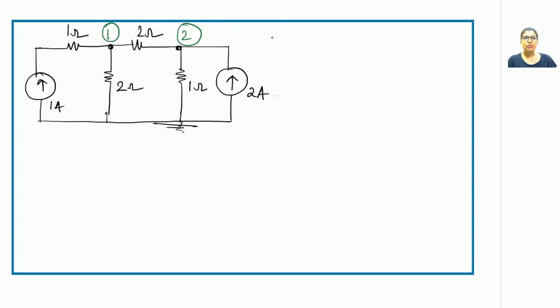So now writing down the KCL equations at that point A, or you can say at node 1. We can name it as node 1. Writing down the KCL equations at node 1. How many branches are connected to this point or node 1? There are 3 branches. This is first, this is second, and this is third branch. So can we write down the equations for these branches?